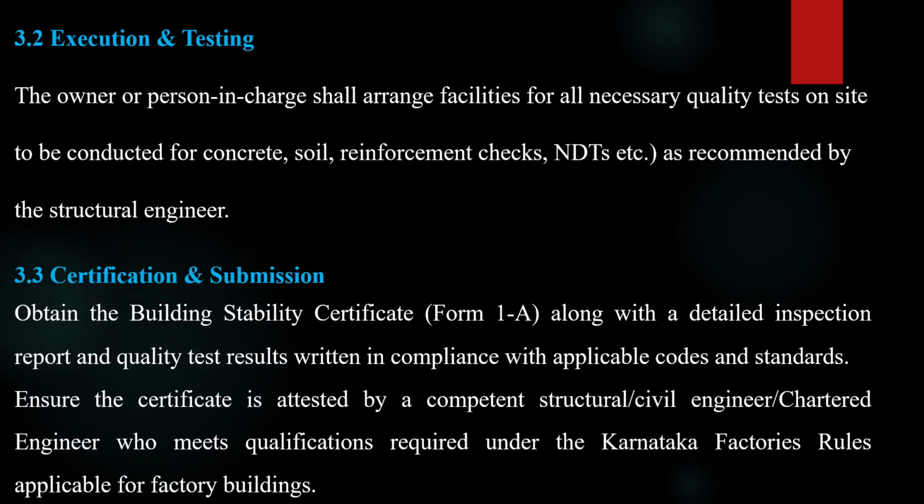Execution and testing. The owner or the person in charge shall arrange facilities for all necessary quality tests on site, to be conducted for concrete, soil, reinforcement checks, non-destructive tests, etc., as recommended by the structural engineer.